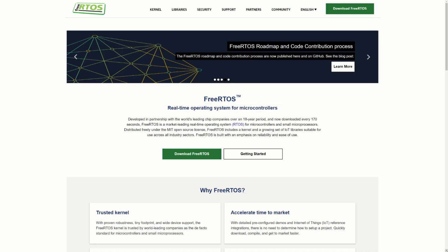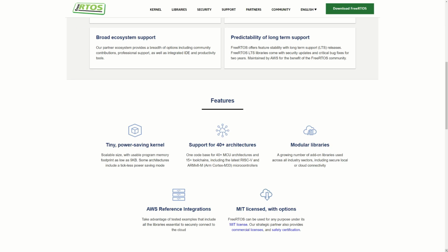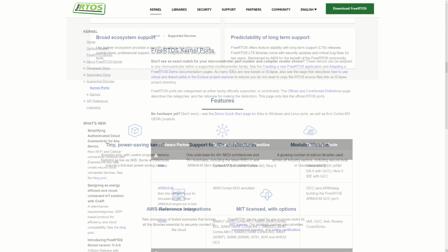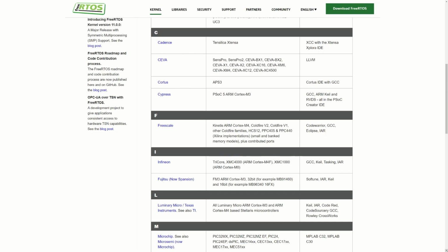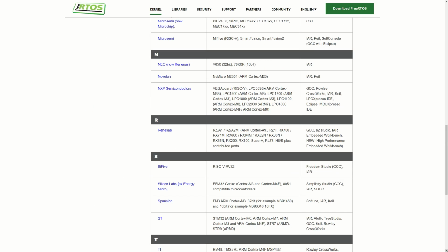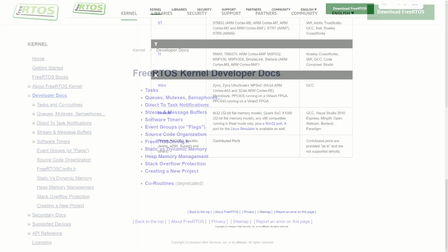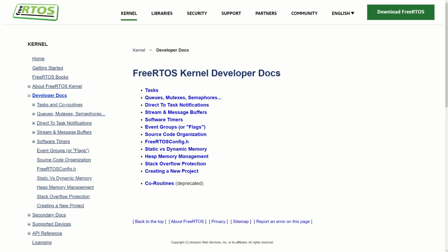FreeRTOS is an open source, real-time operating system for microcontrollers. It may run even on devices having very small amounts of flash or RAM memory. It offers multitasking execution, timers, synchronization primitives for thread-safe communication between the tasks or interrupts known from the big OSs. All of these objects can be created dynamically or statically, depending on the available resources on your microcontroller.